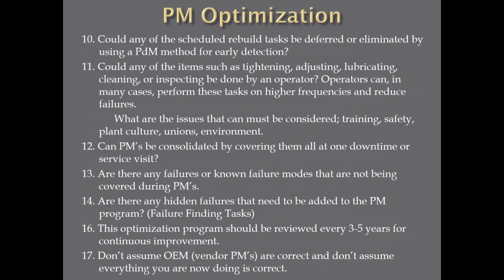Can the PMs be consolidated by covering them all in one downtime or one service visit? A lot of times we can do that. Are there any failures or known failure modes that are not being covered during PMs? You'll find this out sometimes in an RCM or a PM optimization. Maybe we've missed a few PMs. Here's one: are there any hidden failures that need to be added to the PM program? Remember these failure finding tasks.